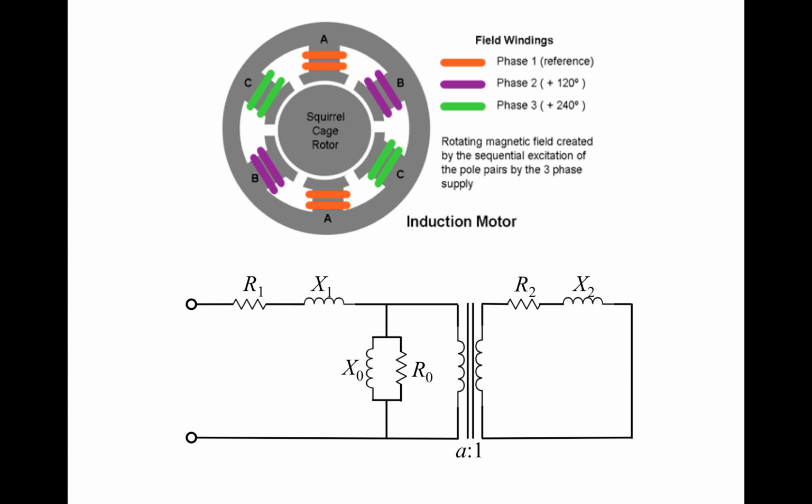There is another effect of the air gap, which is the so-called reluctance of the magnetic flux path. The air gap increases the reluctance of the magnetic flux path. The reluctance is a concept that's similar to resistance. If the reluctance is higher, we will need a higher magnetizing current to induce the same level of magnetic flux.